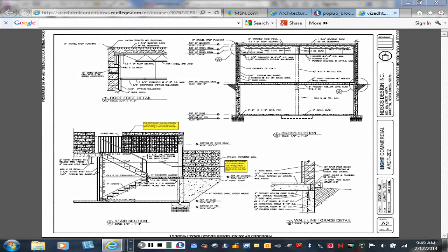So, like I just mentioned, if our overall wall was 12'8" to the top of this exterior masonry wall, then the things that are getting covered up are the steel beam that has to be incorporated into the wall between columns, and then the bar joists that sit on top of that beam.